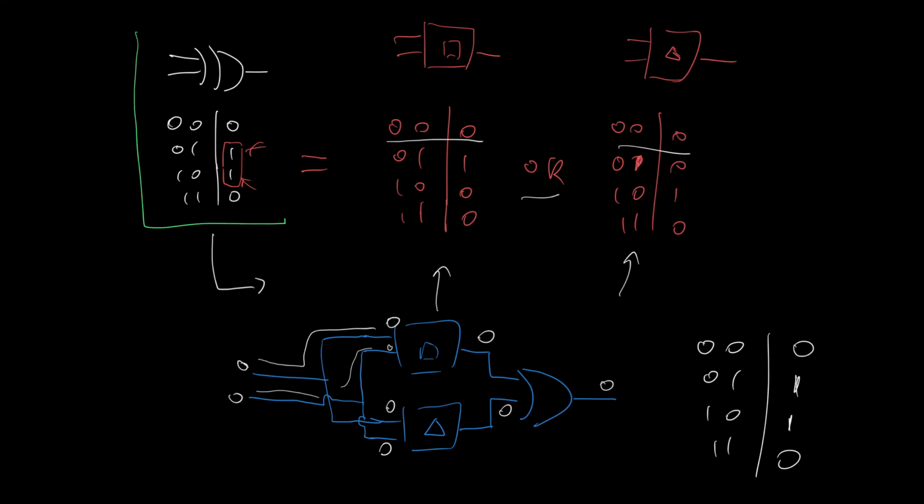Well, the rules of Boolean algebra are that 1 plus 1 is equal to 1, because we define plus to be the OR sign. And for mathematicians, you can actually show that that works. That actually gives you a sensible algebra to work with. Anyway, that situation does not happen here because remember, each of our devices is only going to output a single 1, and by design, different devices output a 1 in different locations.